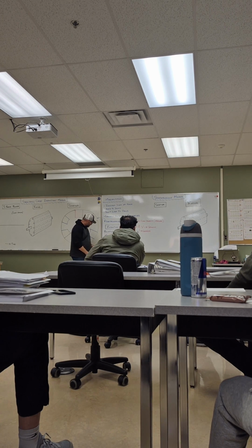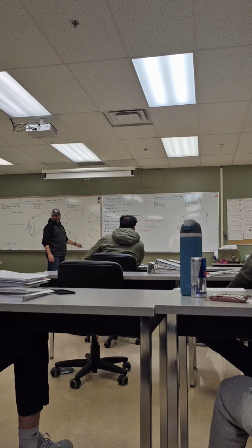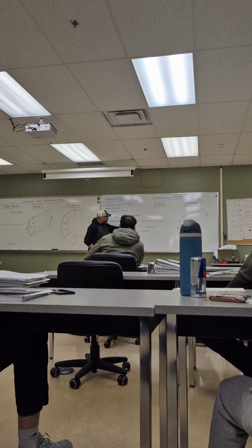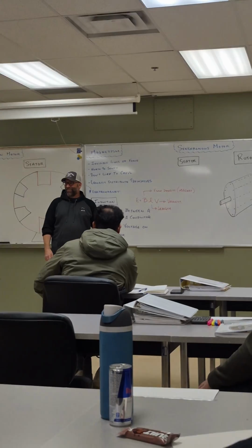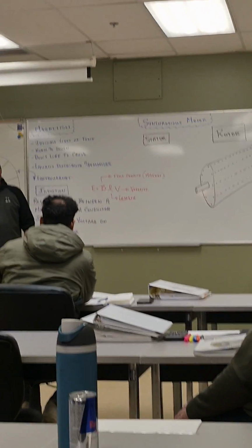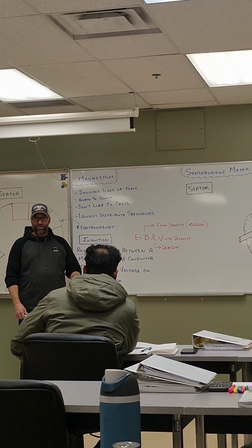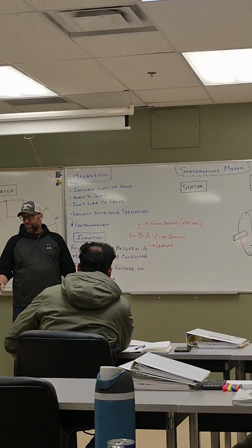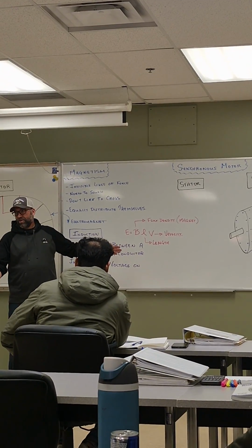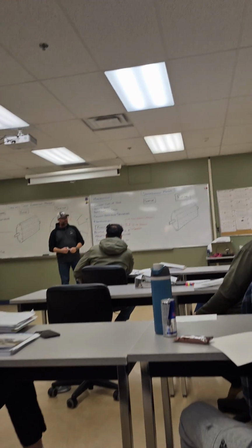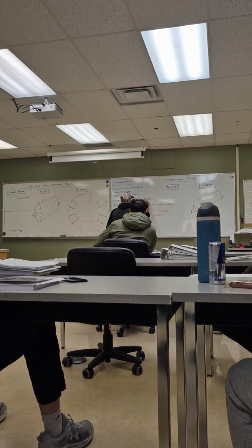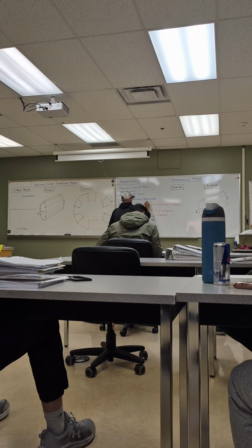Now here's the cool part. That's what we call a direct proportion formula. Yeah, that's awesome. Okay. Any one of these goes up, I increase any one of those three things. What happens to the induced voltage? It goes up. You're like, well, that's sweet. Spin it faster, move it faster, more volts. Add flux density, more volts. Add length, that's really hard to do in a machine that's already built, right? But add more length, more volts. That's cool. Any one of those goes up, any one of them, E goes up.